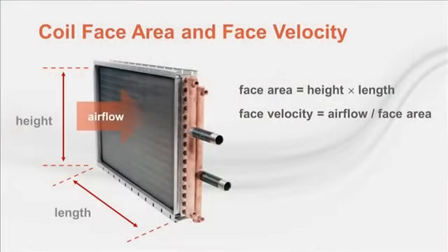The effects of these design choices and constraints become more apparent when we look at actual coil selections. So next, we'll walk through a few example selections, starting with chilled water coils. Brian? As I mentioned earlier, in most applications, the cooling coil also dehumidifies as water vapor in the air condenses on the cold fin surfaces. So it must be selected to prevent moisture carryover, as I talked about with the industry rule of thumb of 500 feet per minute when sizing the coil.